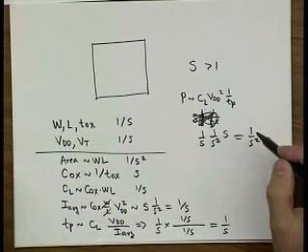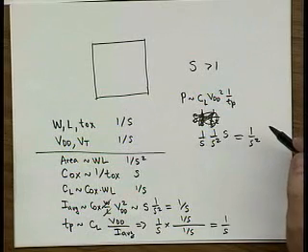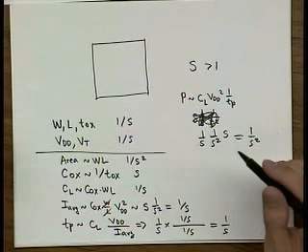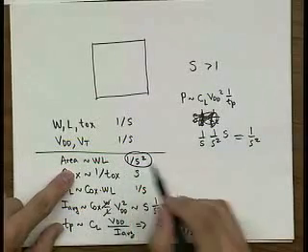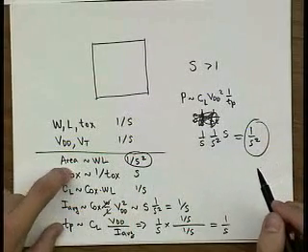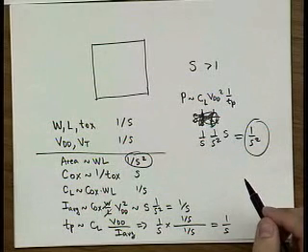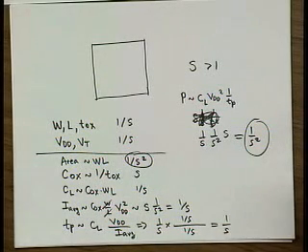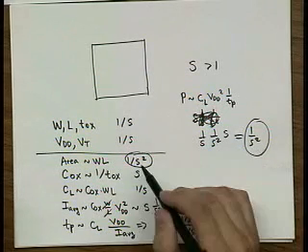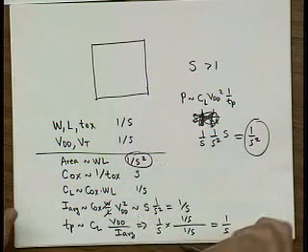Now, the interesting thing is that if you keep scaling everything together, your voltages and your dimensions, and you look at the area and you look at the power, the power per unit area stays constant. So that's the reason why in fixed voltage scaling we had an increase in power density, because we didn't scale the voltage, but we just scaled the area.